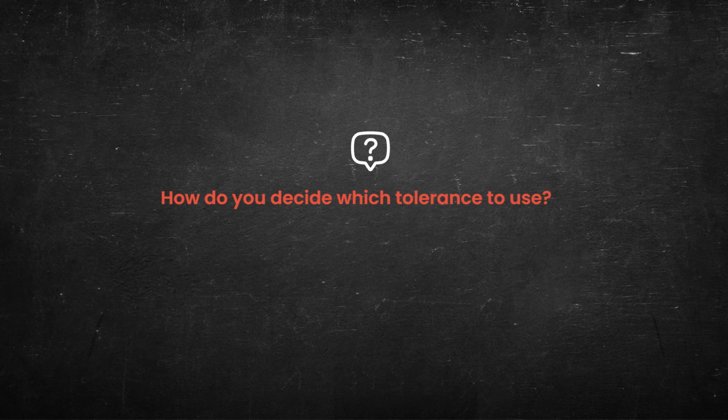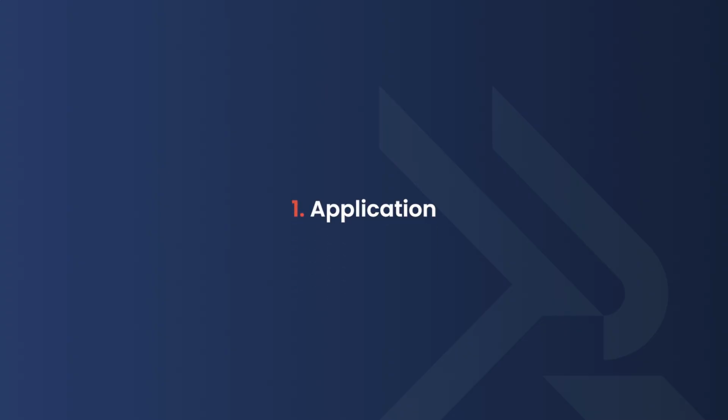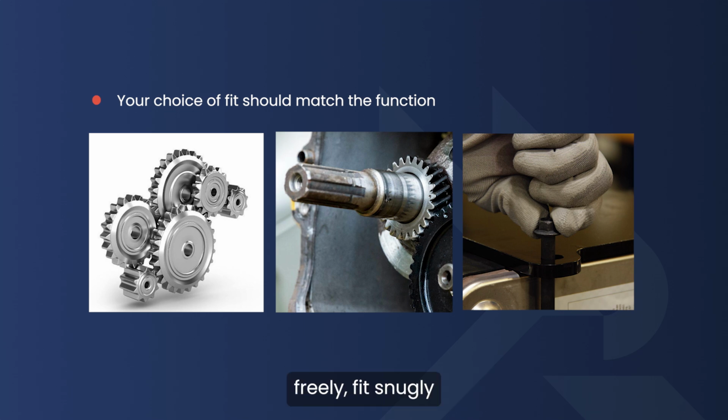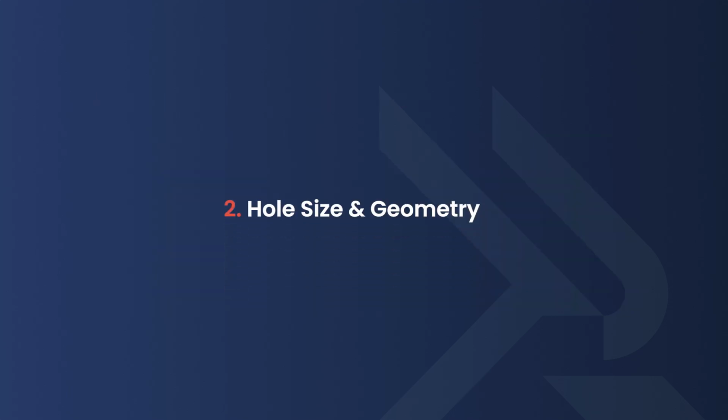Now, how do you decide which tolerance to use? It depends on 3 key factors. 1. Application. Does the part need to move freely, fit snugly, or be permanently locked in place? Your choice of fit should match the function. 2. Hole size and geometry.